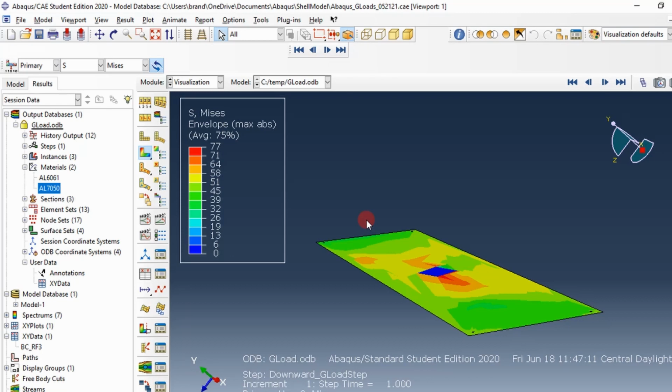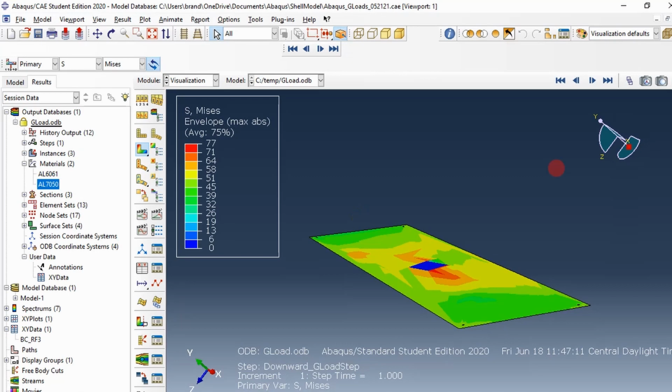and that's how you do some post-processing on some metallic materials. Of course, keep in mind this was just a demonstration of a quick workflow to run an acceleration load analysis. Of course, there's a lot of grunt work left that should be done in this case, such as mesh refinement and making sure the results make sense and eliminating any singularities that may exist. So just keep that in the back of your mind. All I wanted to show in this case was how to run unit GLoads for a linear analysis and post-process the results. And this, what I showed here, is how it would be done.